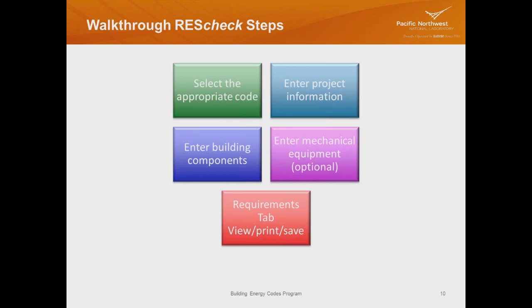So you'll want to know the building envelope components. And then mechanical equipment, it's optional anymore. There are no trade-offs for mechanical systems in the most recent energy codes, and you don't need to enter mechanical equipment. It needs to meet minimum efficiencies regardless anyway. And the software does not do load calculations. So within the codes, doing load calculations on HVAC sizing or duct design and duct sizing, REScheck does not do that. You would need to use another mechanism to do those calculations.